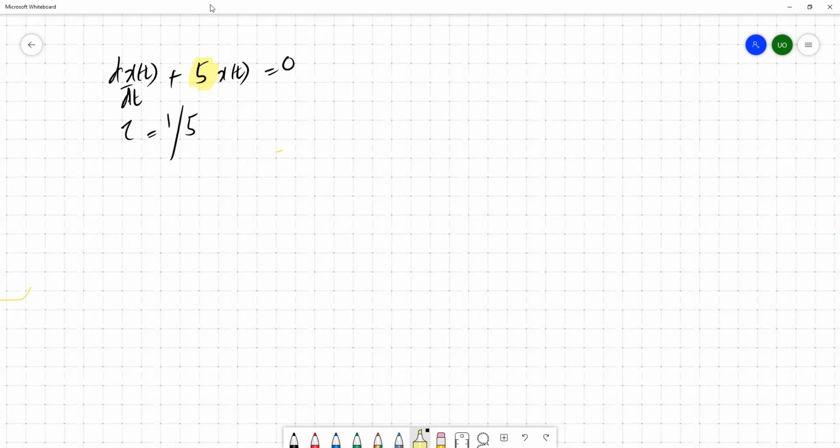So by looking at the circuit, we can easily evaluate the time constant. But there may be certain circuits you cannot simplify to a first order circuit. Even if they are first order circuits, there may be multiple capacitors. We can sometimes simplify it to a single equivalent capacitor, but it's hard to find a way of reducing the number of capacitors. Depending on the configuration of the circuit, sometimes it's hard to simplify the circuit to a single resistor or a single capacitor.